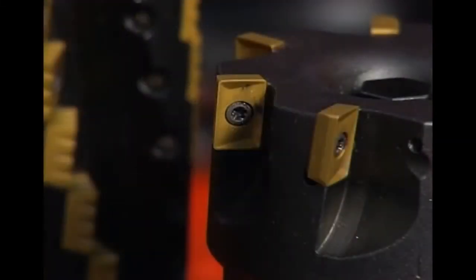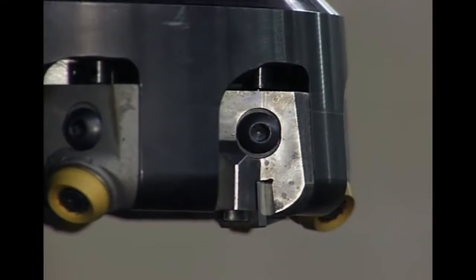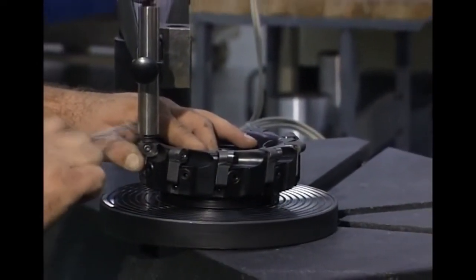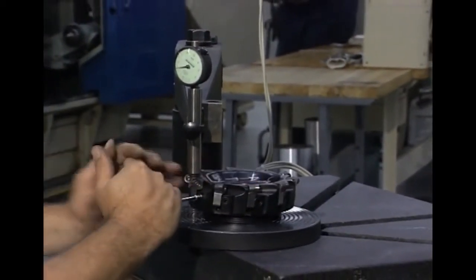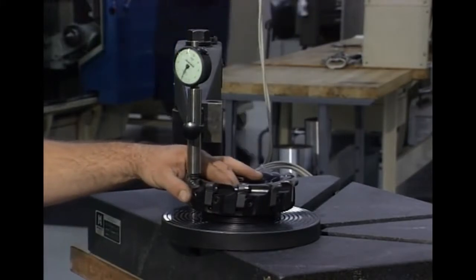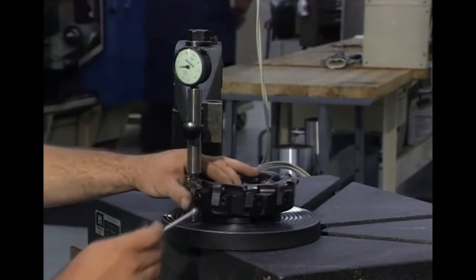In addition, milling inserts have their own corner geometries, including the radius and the wiper flat. A large corner radius produces a finer finish than a small radius, but a corner wiper flat on the insert produces the finest surface finish. Sometimes a single wiper insert in a cutter will improve the surface finish, even if all the others are roughing inserts. For best surface finish and longest tool life, all inserts must be preset to carry an equal load. One or two inserts protruding further than the others will carry the cutting load and wear out prematurely.